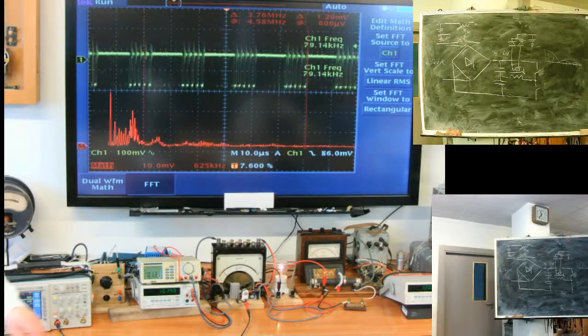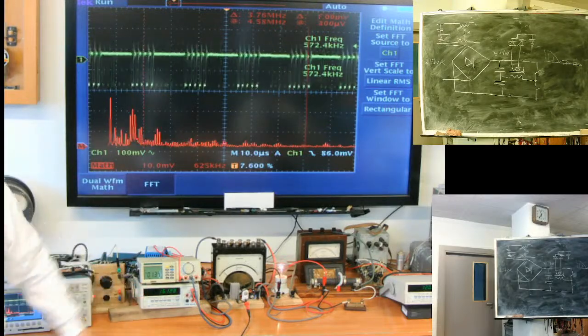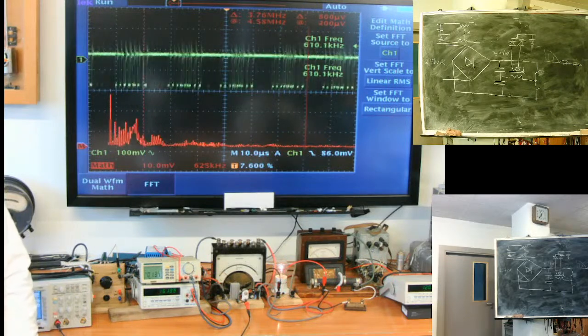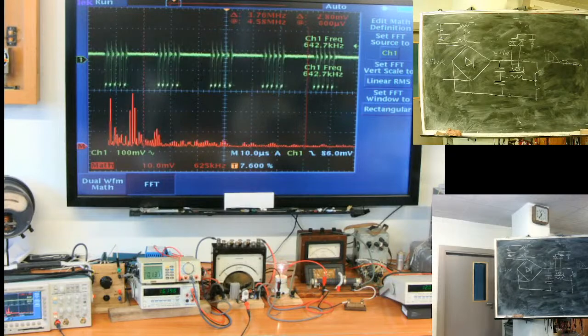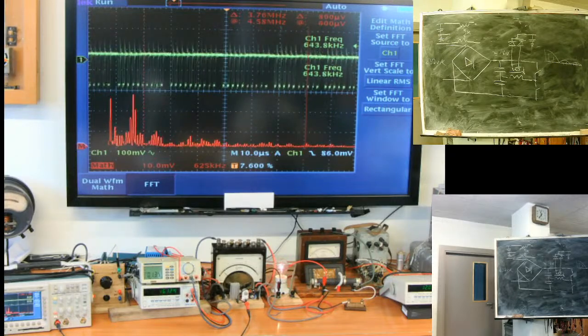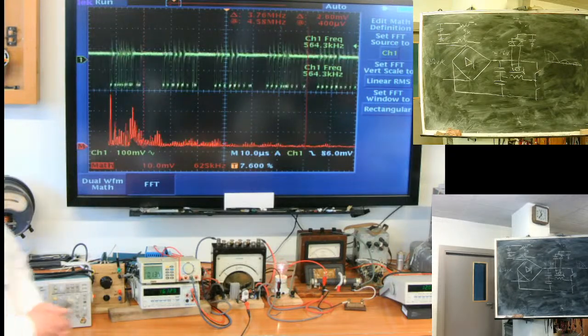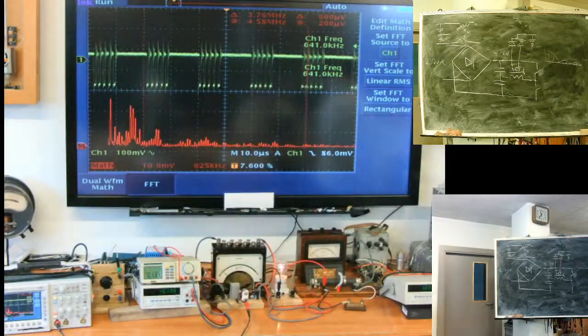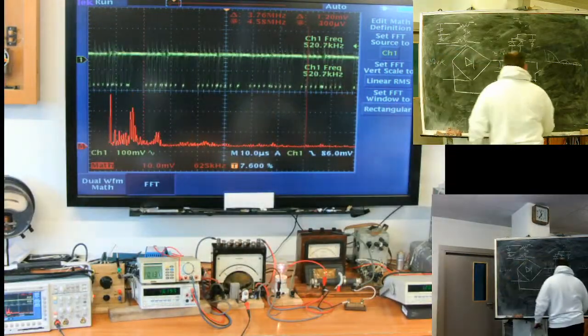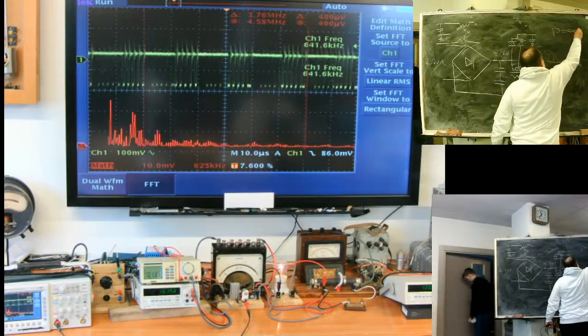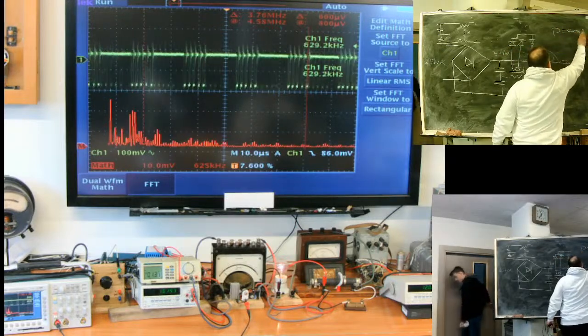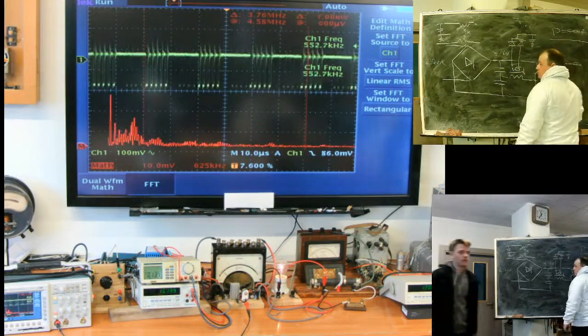Why? Because this thing is not a resistance. Its reaction to voltage is determined by the control strategy of the PWM. This is not a constant resistance law, but it's much closer to a constant power law.